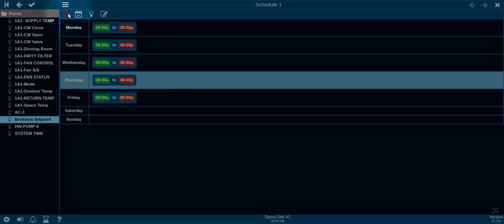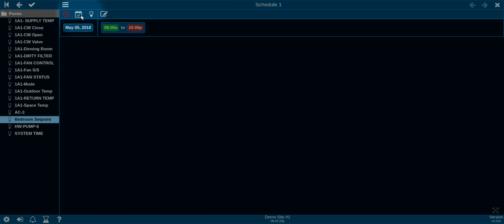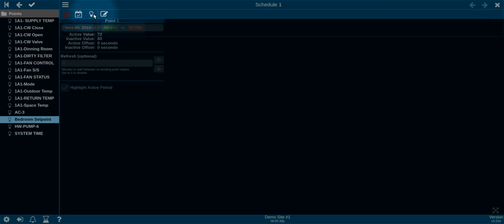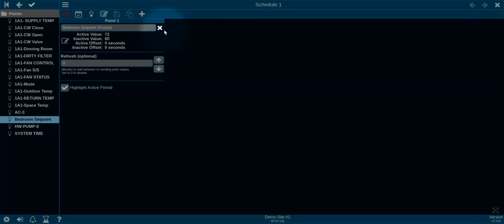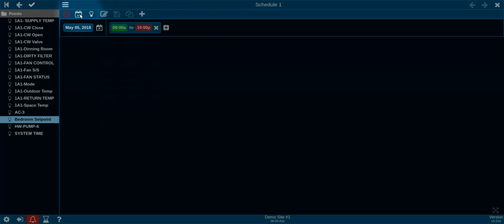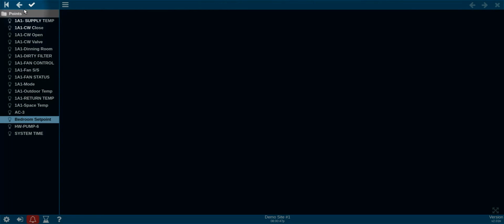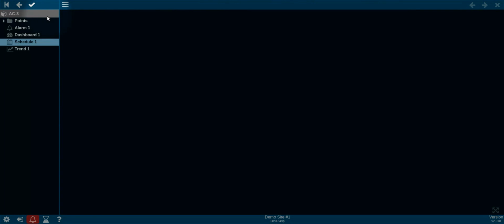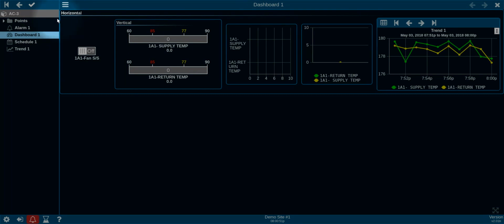So you have your weekday schedule and your exception schedules. And you can add other points also. It will take 32 points for each schedule. And that's pretty much all you have to do with it. It runs by itself, and will change the point values at the right time.